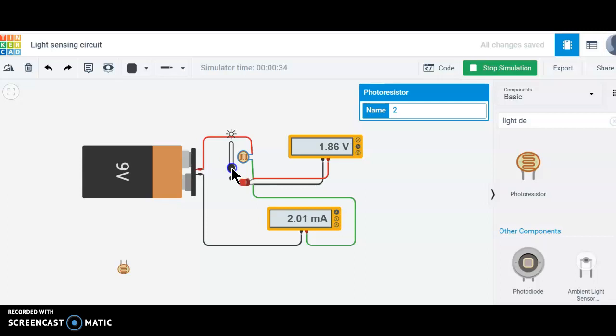it goes to 2 milliamp and then keeps going up. 6 milliamp, 7, 8, 9, 10. Okay, the maximum is about 13, 14 milliamp, which is still below the maximum acceptable current. A red LED like that can take up to 20 milliamp without damaging it, and it probably is at full brightness. So in this circuit, it's not at its full brightness yet.